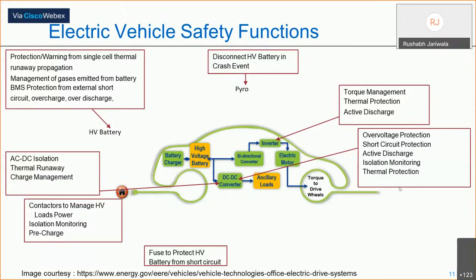So active discharge is a function expected out of all of these loads: when there is a crash event, it should discharge all the energy remaining in the bulk capacitor in a very short period of time, and that is typically 5 seconds. So one needs to think about that when designing such components, let it be inverter or DC-DC converter or sometimes OBC as well. So after that, let's go to the next one.